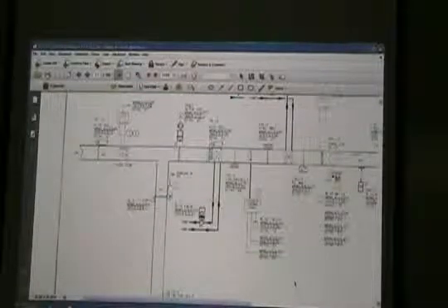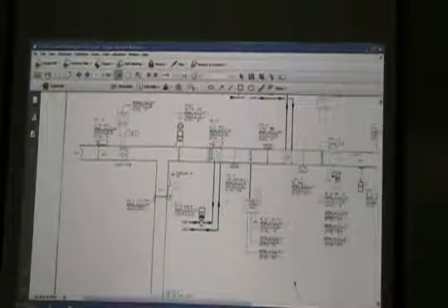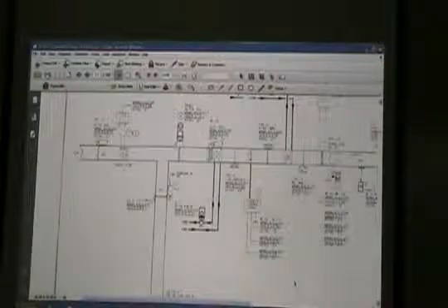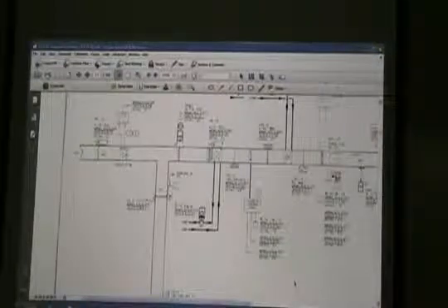of outside air. So this is some type of device. It could be a pitot tube, it could be an electric element that's sensing temperature and velocity, converting it to airflow. Some type of device that's always giving us an airflow measurement. So through the programming, we'll modulate this damper constantly to maintain a certain airflow right there. The outside air damper should be modulated to maintain specified scheduled outside air.